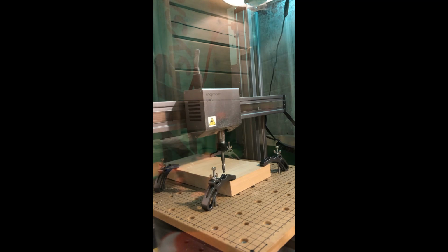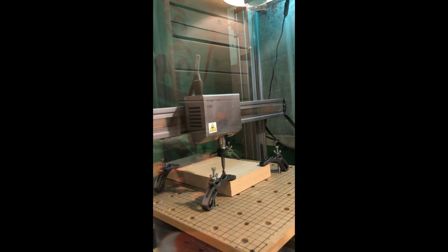Now what I want to do is lower my head or my Z axis 10, right there. Now that is the actual top of your material and you are in your home spot. So now that you're at that again, go back over, set your Z origin only back to 0 again, or you can just hit the set work origin right here. It really doesn't matter. Either one works just as good because you're in your final position. Now you're ready to go. Run your job.